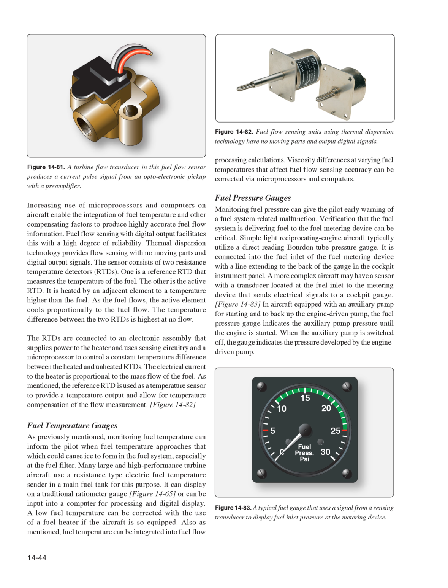The electrical current to the heater is proportional to the mass flow of the fuel. As mentioned, the reference RTD is used as a temperature sensor to provide a temperature output and allow for temperature compensation of the flow measurement. Figure 1482, fuel temperature gauges.